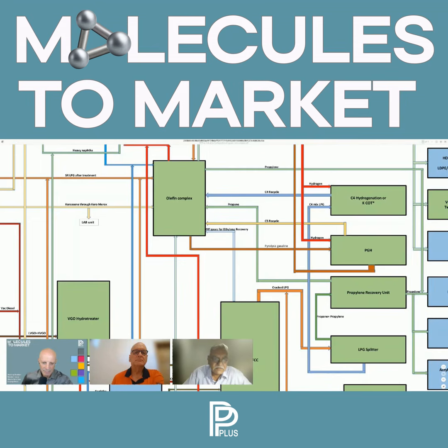So, for example, we will do mechanical thermal design of all heat exchangers and air cooler designs. We will do the front-end mechanical design of an equipment, column, vessel, etc., so that we are able to assess the hardware. So for each unit, we do that and cost it out. So we have a good hang of what the equipment is, what the quantum of work involved is, and that is how we cost it.